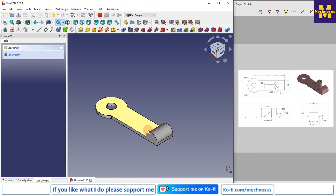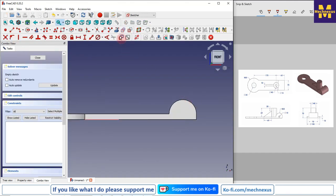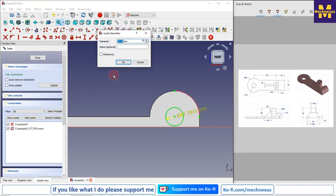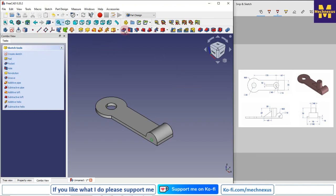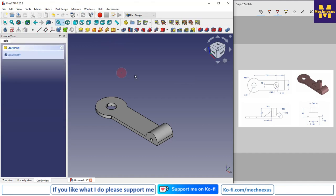I will say OK. Now we want a hole here which is of diameter 10, so I will select this face and I will create a sketch, and I will project my outer arc, and now I will draw a circle. So it is a diameter 10, so I will select this and give it a diameter 10, and I will close it and I will say extrude and I will say through all, say OK.